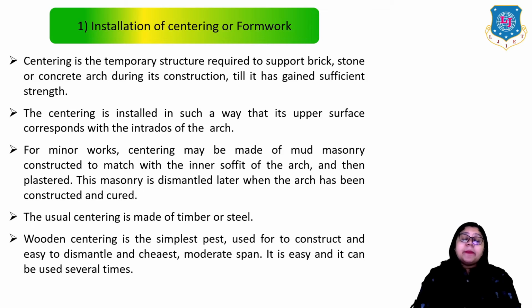Centering is the temporary structure required to support a brick, stone or concrete arch during its construction till it has gained sufficient strength. The centering is installed in such a way that its upper surface corresponds with the intrados of the arch. For minor works, centering may be made of mud masonry constructed to match the inner soffit of the arch and then plastered. This masonry is dismantled later when the arch has been constructed and secured. The usual centering is made of timber or steel.